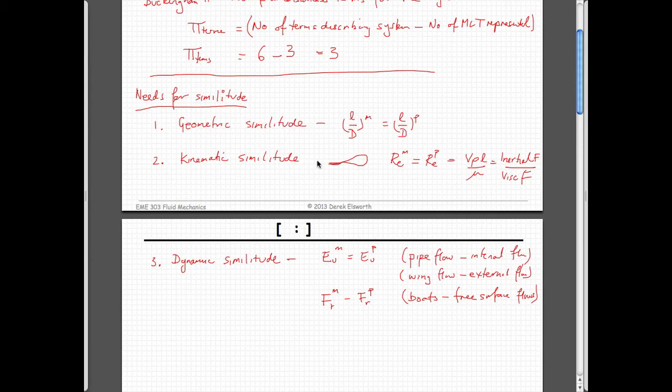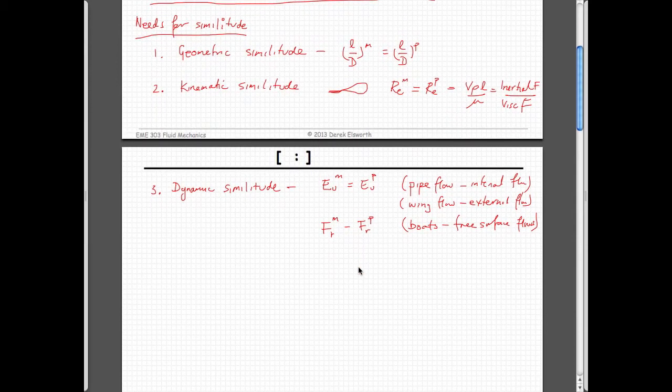We're going to make sure that we match the Reynolds numbers between model and prototype, so this is probably one of the pi groups as well, the second one. And if we want to know what the forces are that apply on this, then the other potential pi group is possibly going to be the Euler number. And so we have 3 pi groups. You could do it by Buckingham Pi. Depending on how you choose your primary and secondary variables, you'll get different results. In a test, typically you'll be told to use this as your primary variable just for ease of marking, so that you all get the same result. But you don't have to, it's not preordained.